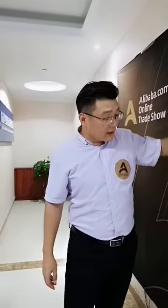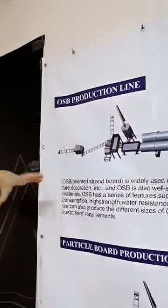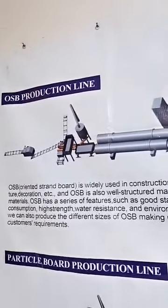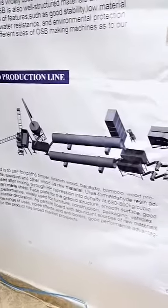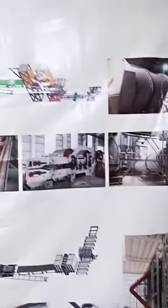So now, there's also a difference between OSB and particle board. First, for OSB, the first machine is a long axle peeling machine, to make veneer from the log, the wood. So for OSB, the raw materials are stricter. They always need long logs and wood and some big branches. But for particle board, it's okay. Even smaller pieces, even some roots of the tree, some limbs, and some very small branches can be used as the raw material.